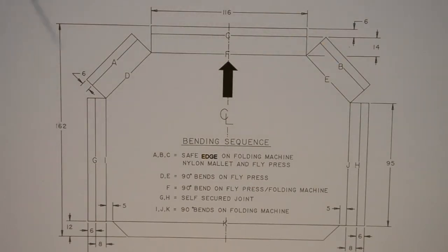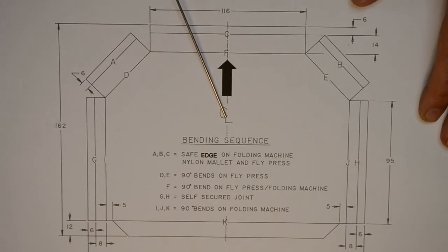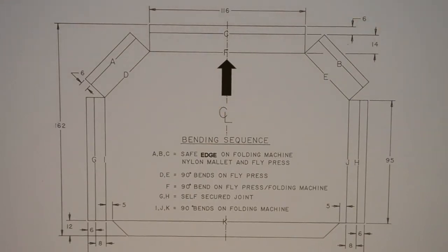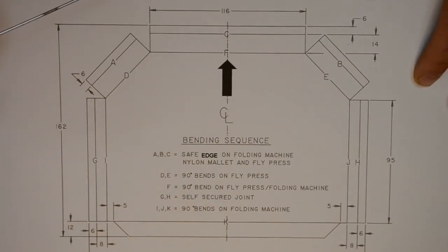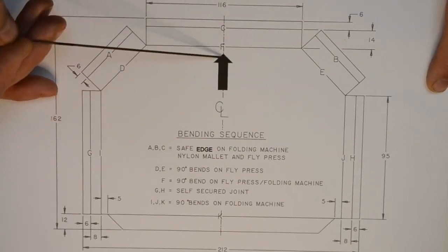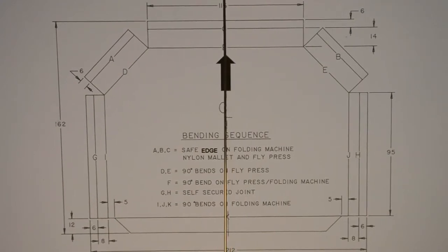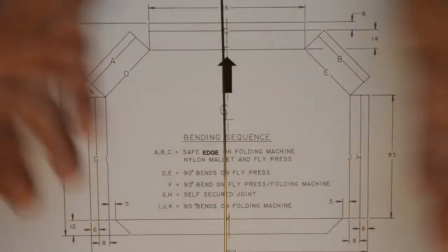Well, actually the datum is slap bang in the middle of it, and if you've done enough research into BS 8888, the ISO standards, etc., you may be familiar with this symbol. This isn't just an abbreviation, it's a specific symbol. So we have a C crossing over an L, and what that specifies is that what we have here is a centre line. It's unfortunately been obscured by a lot of this other writing that we've laid over the top to help you follow the folding technique, but nevertheless you can see there's a dotted and dashed line running through here, running up through here, underneath the big arrow and up to the top, and that is slap bang in the middle of what is a symmetrical component. If we folded that in half, the two edges would line up.